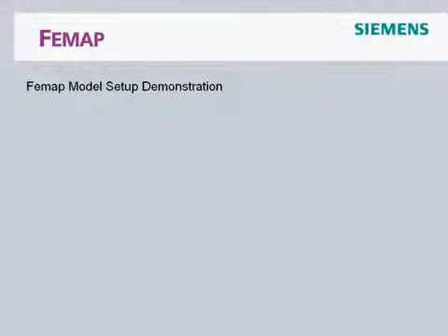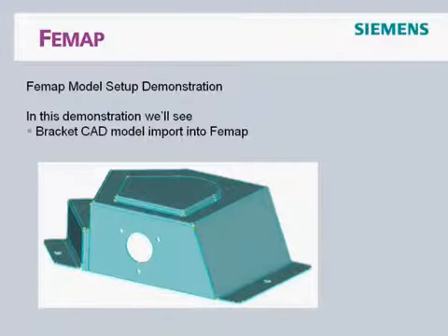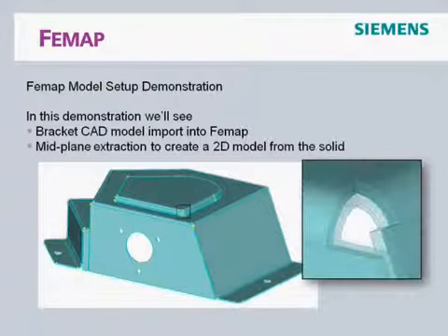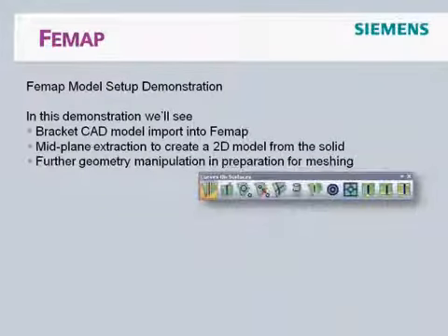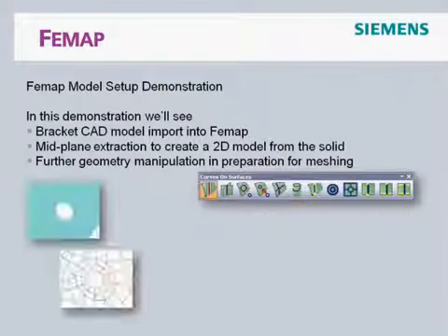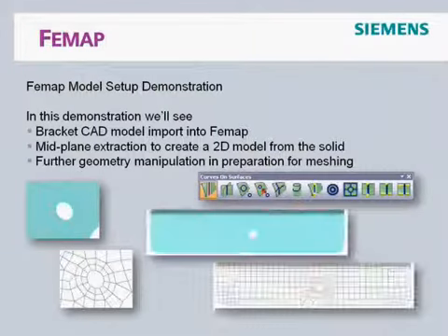Welcome to the FEMAP model setup demonstration. In this demonstration, we'll see a CAD model of a bracket imported into FEMAP, the resulting solid converted to a mid-plane surface model, and some further geometry manipulation in preparation for meshing and creating a shell FE model.